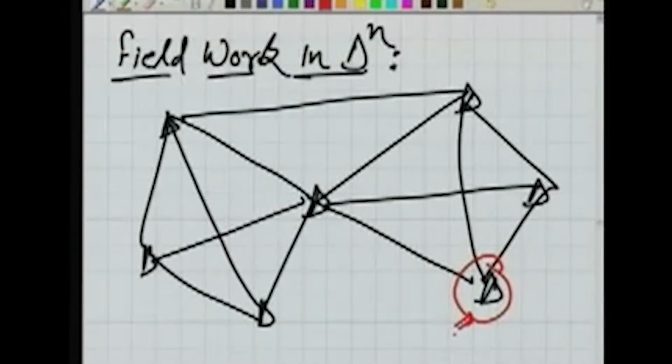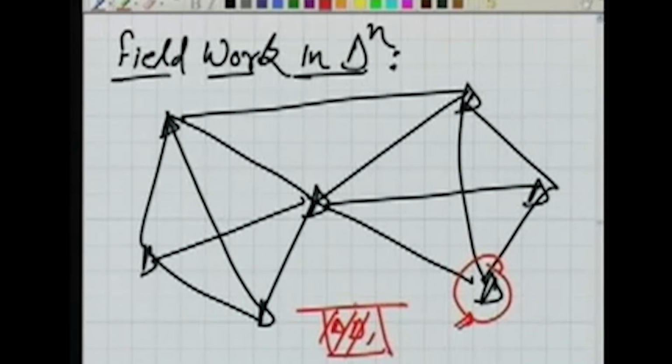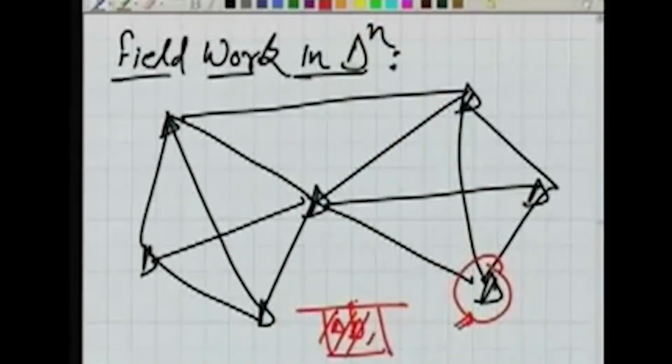Once you have decided, okay, this point is going to be a triangulation station, what do we do? We put a concrete block in the ground, and on top of this, with a nail, we mark that this is the station. We will center our theodolite here, we will put our signals here. So we mark these points in all the places.